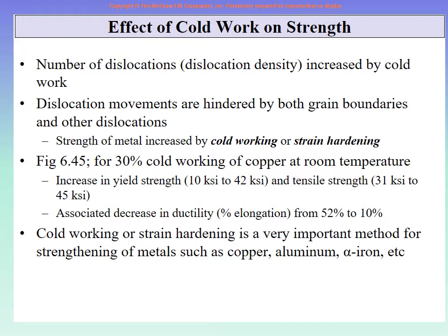Now, if you remember, when we were doing the full stress strain diagram, at the end of the tensile test and everything, then we divided it into some portions: this is the elastic portion, this is the yielding portion if there is a flat yield line, this is the strain hardening portion, and this is the necking region.